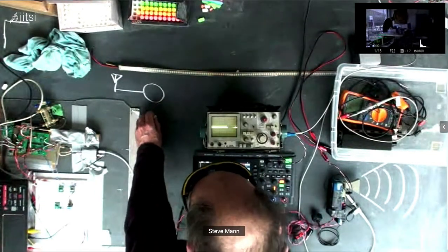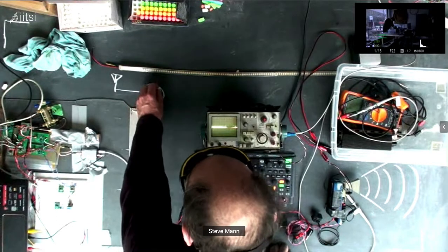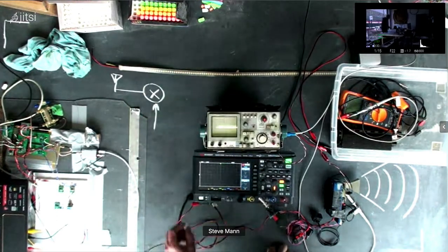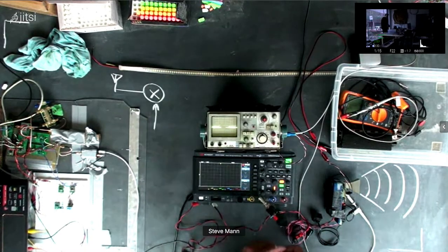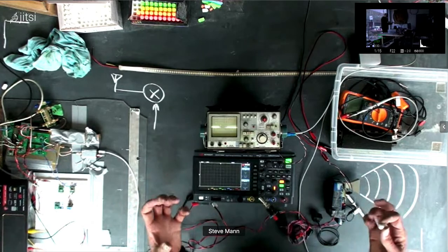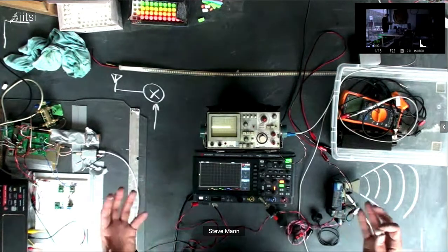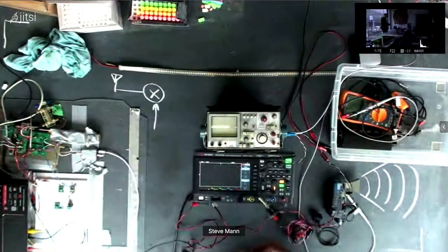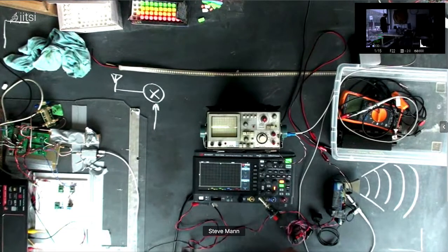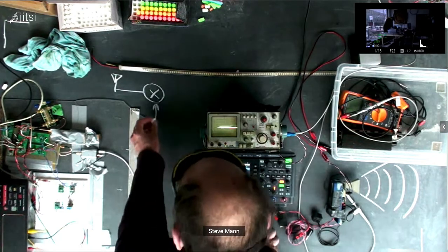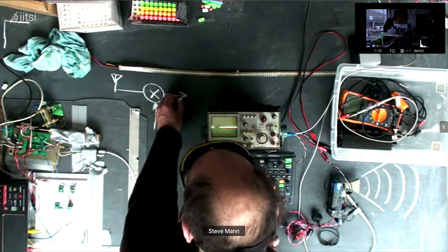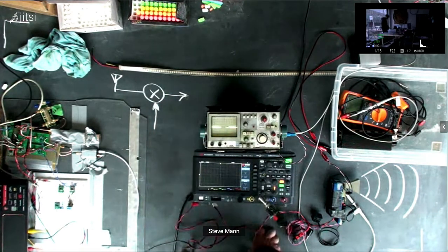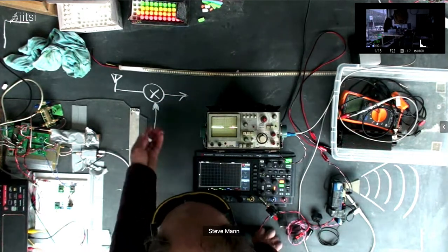And we have a modulator or multiplier, a mixer. In radio, mixing means multiplying. In audio, if you're a disc jockey and you have two record players, a mixer means adding. A mixer is a device that adds some things together. But radio engineers usually think of a mixer as something that multiplies signals together. So the result is sum and difference frequency components. In the frequency domain, you have the sum and difference frequencies appearing when you multiply two things together.